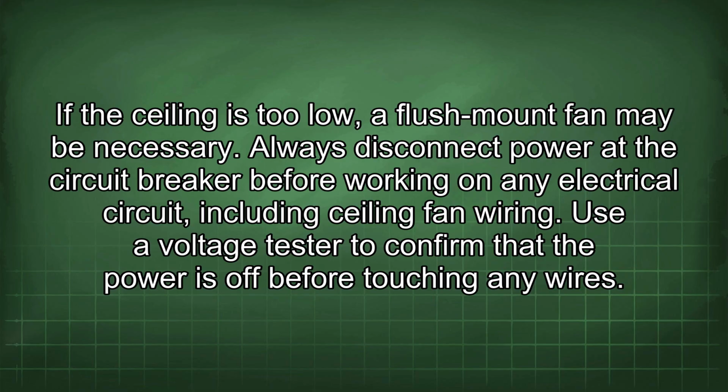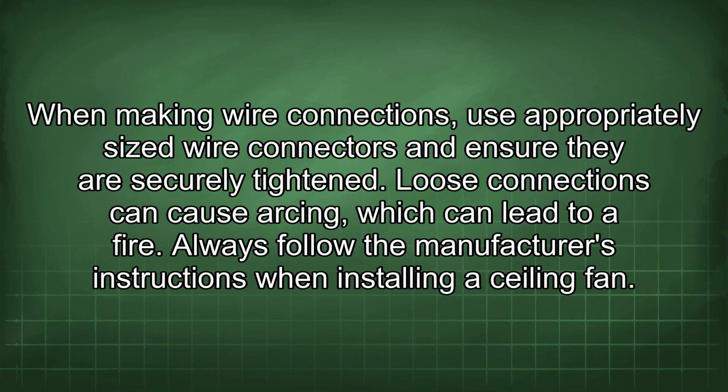Always disconnect power at the circuit breaker before working on any electrical circuit, including ceiling fan wiring. Use a voltage tester to confirm that the power is off before touching any wires. When making wire connections, use appropriately sized wire connectors and ensure they are securely tightened. Loose connections can cause arcing, which can lead to a fire.